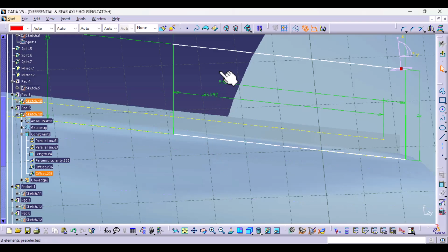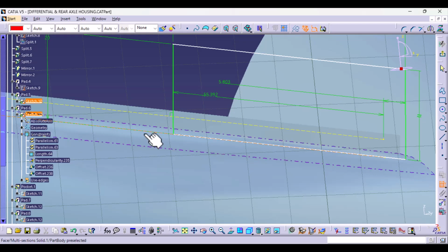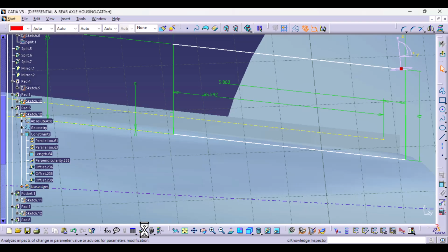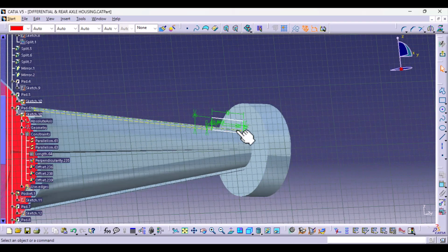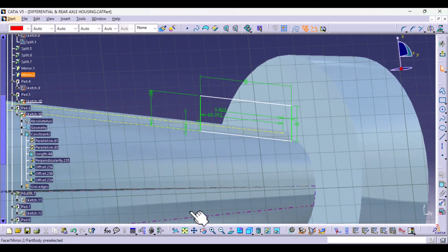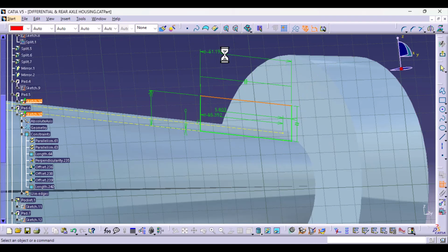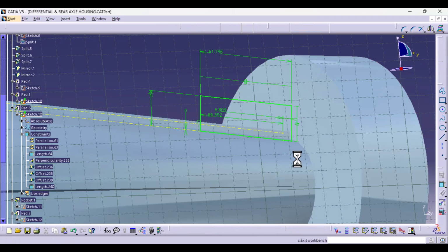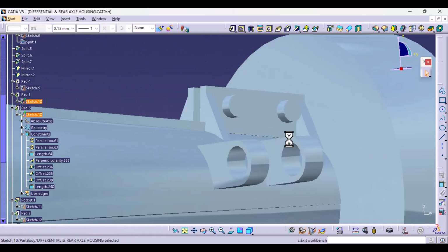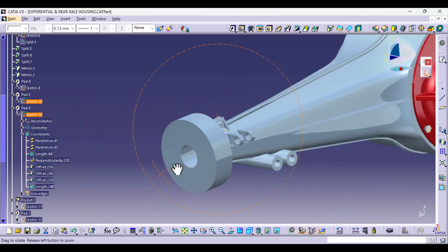Then you want to control the vertical positioning. So you can say the distance between this edge and this horizontal edge is 0. So that makes sure that when we make edits, this sketch will move relative to our geometry. You can also add the horizontal, but I think that is already governed. It will be over constrained. Oh, if you can add it, that's fine. So I exit. Now I'm sure that if I scale my model, this will move relative to its original position.